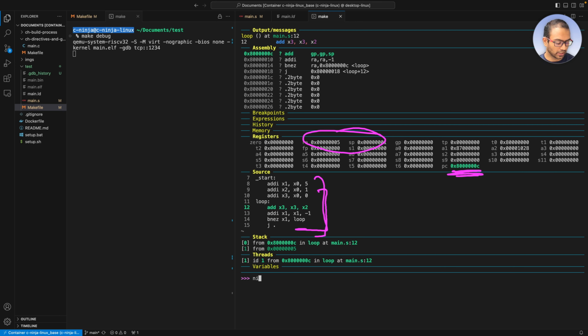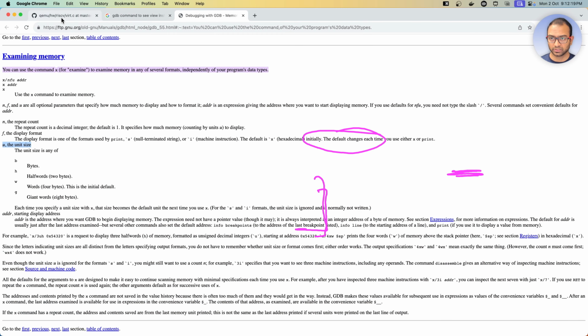So with this, hopefully I should have convinced you about a couple of things. First, we made some modifications to the Makefile to eliminate the usage of the linker script, and then we generated an ELF out of it, which was loading the program at hex 10,000 or 1054 address. And then after that, we analyzed how it produced the ELF without the linker script, and that had to do with an internal linker script that the linker uses. We explored the idea of a memory map and reasoned about the ROM code and the DRAM memory location. And now hopefully I've convinced you that a linker script is required to put our code at the start of the DRAM region.